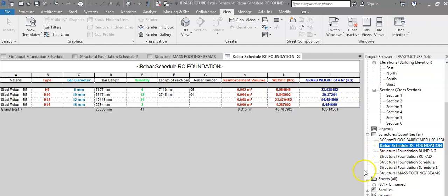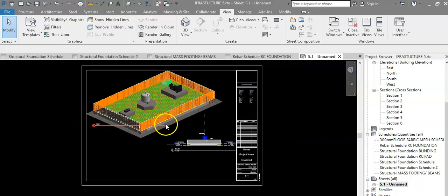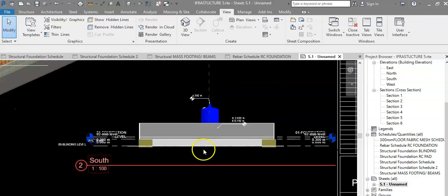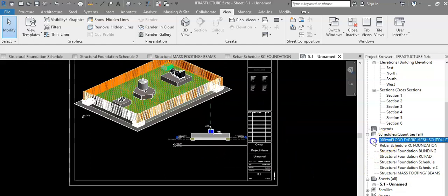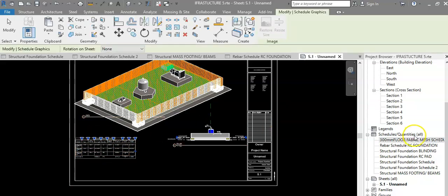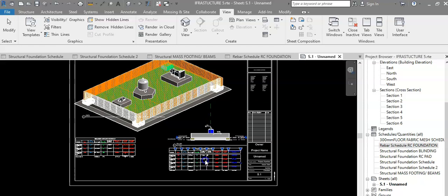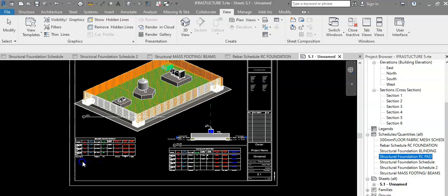Having done that, one final thing is we can produce a sheet here, a sheet of work, and basically we can put the view of the project with any other view, like for example this elevation, and on top of that we can pass on some information regarding this scheduling, like what you see here, 1 and 2, and you can organize them the way you like, to be represented to the client or to the whole team and the management.